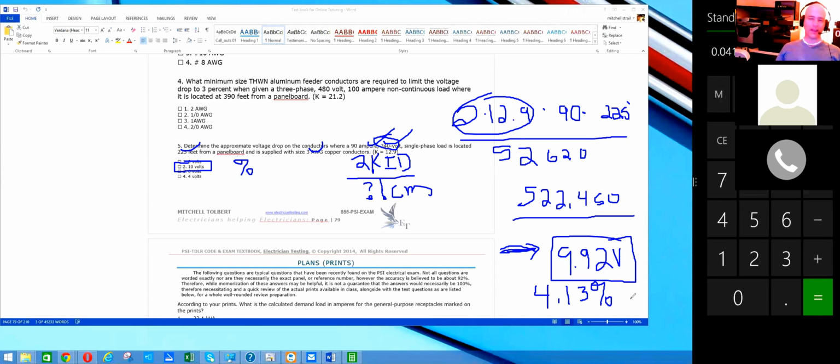So that's probably the toughest part. Very seldom do you get that part of it out of any book or practice. I guess they kind of leave that to your own final judgment. But for me, sometimes that was the hardest part. If they're asking me for percentage, to convert that is real simple if you know how to do it. So as a note, I would probably put that down as a step, just to remind yourself the answer will always be in a real value, and to get the percentage, just simply divide your answer by the system voltage, and that'll give you what that represents percentage wise. Which we know that for a branch circuit, that's too much, right?